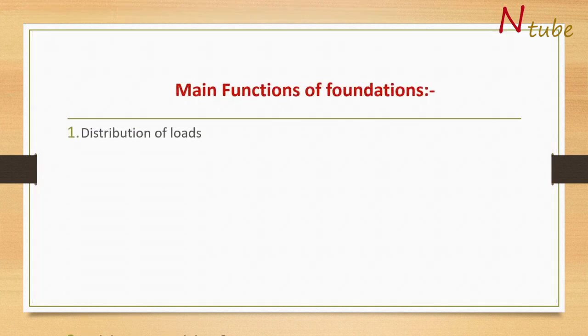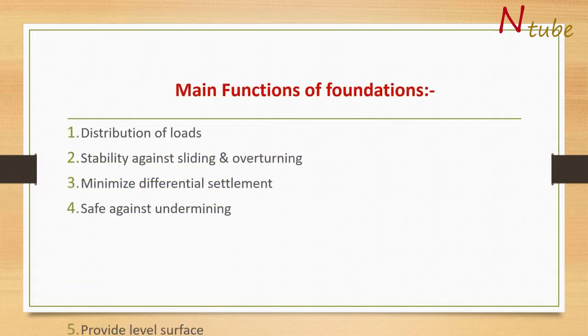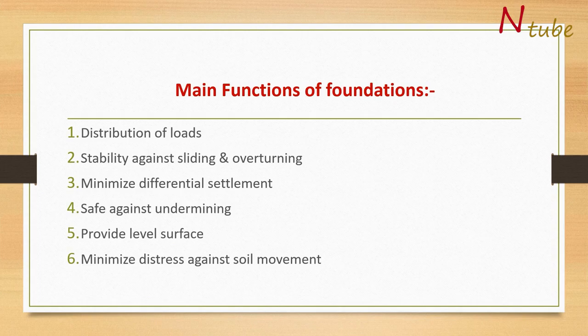Main functions of foundations. Distribution of loads. Stability against sliding and overturning. Minimize differential settlement. Safe against undermining. Provide level surface. Minimize distress against soil movement.